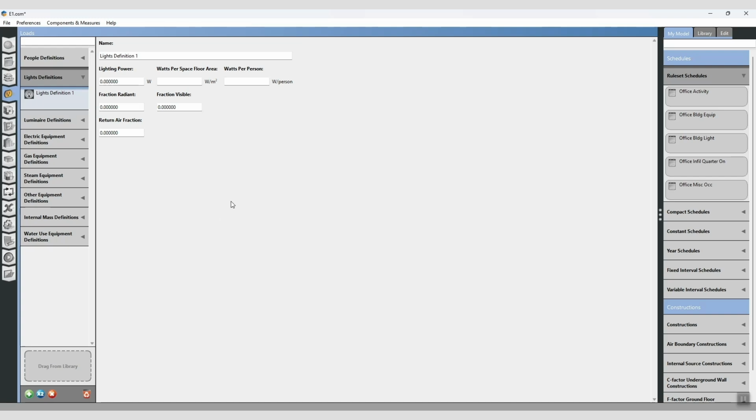One final key point about the thermal side. In EnergyPlus, 100% of the electric energy consumed by lights is eventually rejected as heat to the environment. There's no useful mechanical work done, and almost no storage. That heat is split into four fractions that you can customize. Fraction radiant, long-wave radiation emitted to room surfaces. Fraction visible, short-wave radiation, the light you actually see, that eventually gets absorbed by surfaces. Return air fraction, heat carried away by air leaving the space and entering the return duct. Important for plenum integrated fixtures. Fraction convected, heat directly warming the room air volume.